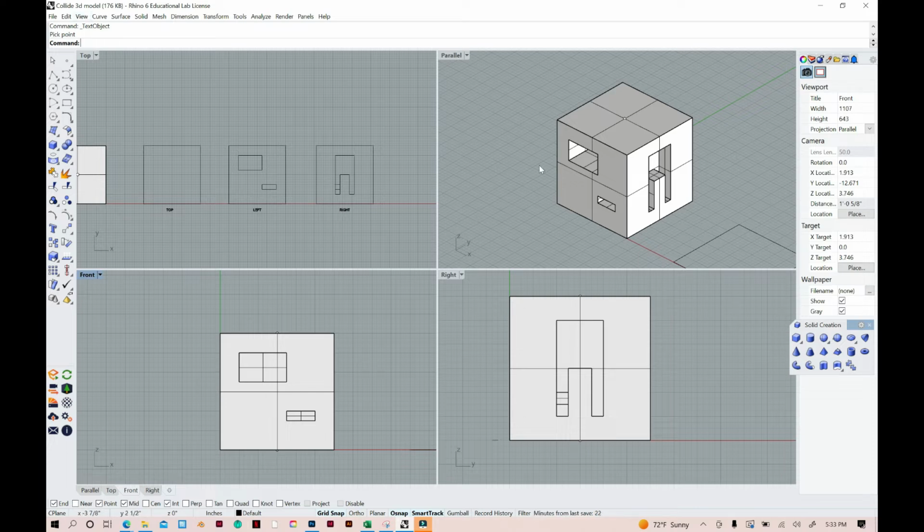So what we're going to do is we're going to cut our model horizontally. Plan. Horizontally is plan. We're going to cut our building horizontally so we can see what's happening inside. A nice rule of thumb, at least for this project, is to cut halfway through our shape.